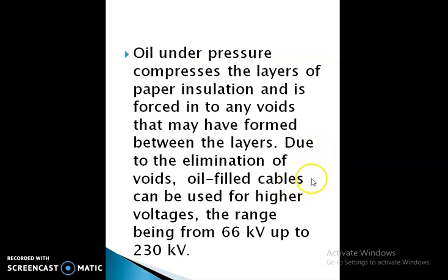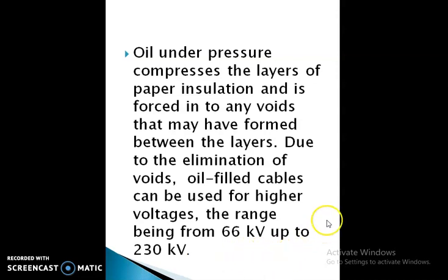Next, oil under pressure compresses the layers of paper insulation and is forced into any voids that may have formed between the layers. Due to the elimination of voids, oil filled cables can be used for higher voltages, the range being from 66 kV to 230 kV.